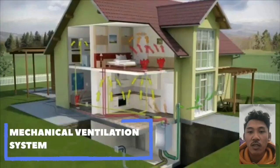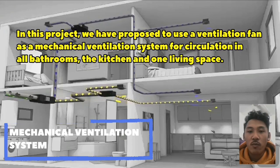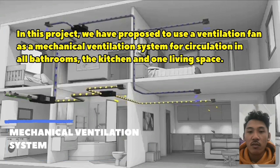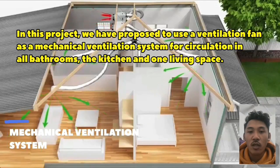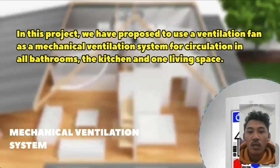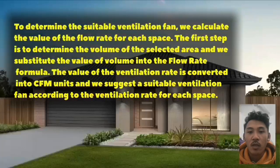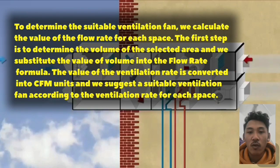Next is the mechanical ventilation system. In this project, we propose to use ventilation fans for air circulation in all bathrooms, kitchens, and one living room space. To determine the suitable ventilation fan, we calculate the flow rate for each space.